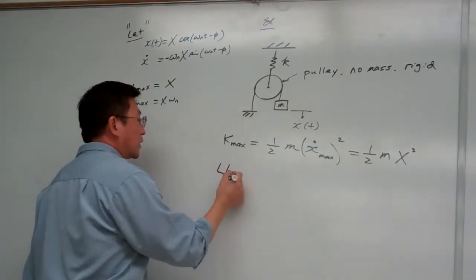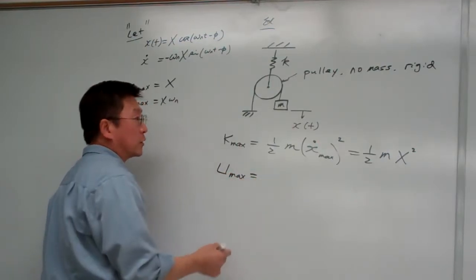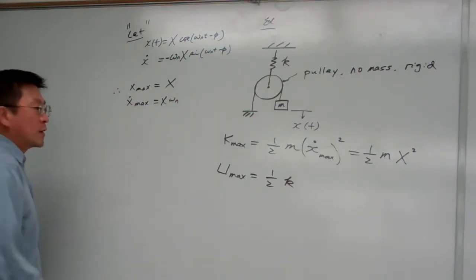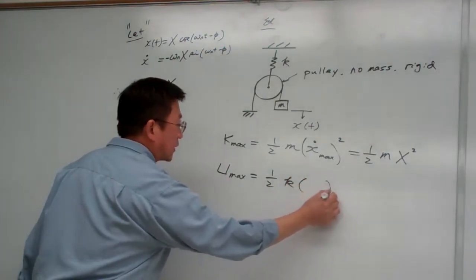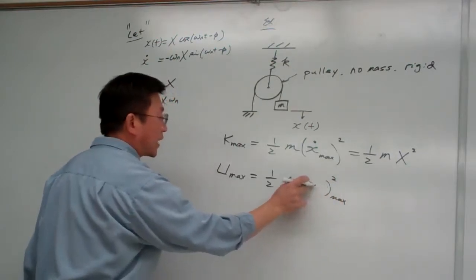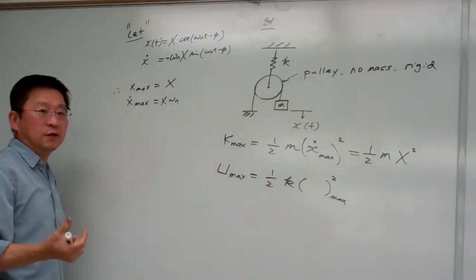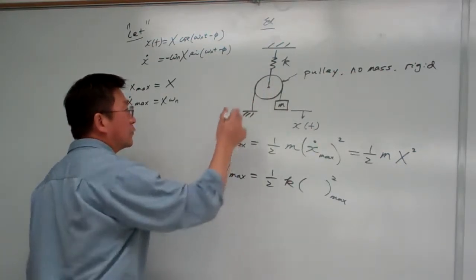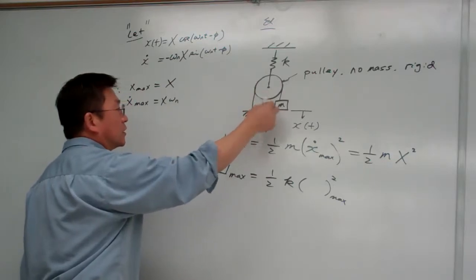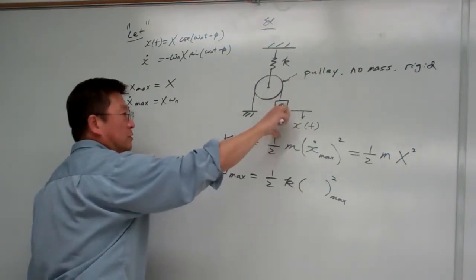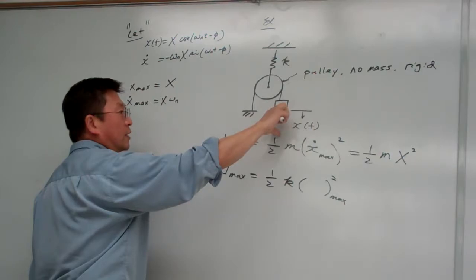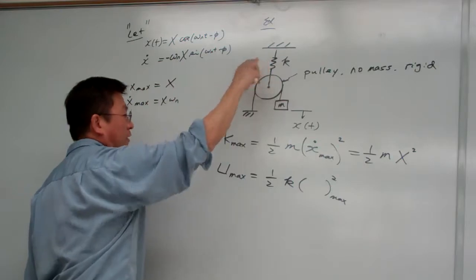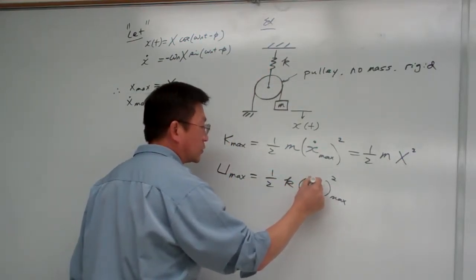And also we formulate the potential energy. Potential energy from here is K times, again, that term is a certain maximum square, and that term represents the deformation of the spring, right? Deformation of the spring, if you remember for this case, the twice amount on the mass block movement equals half the amount of that spring. So here the spring deformation is x over 2.